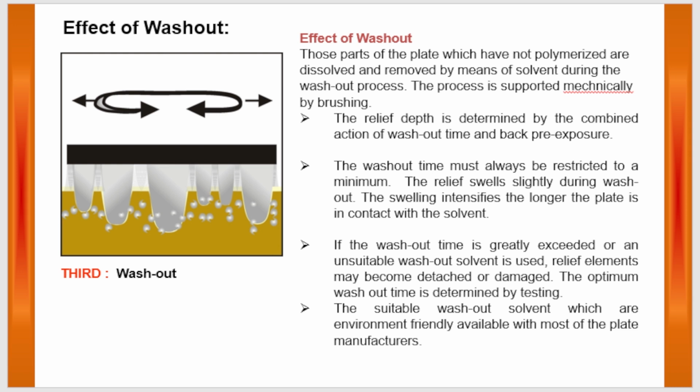The swelling intensifies the longer the plate is in contact with the solvent. If the washout time is greatly exceeded or an unsuitable washout solvent is used, relief elements may become detached or damaged. The optimum washout time is determined by testing. Suitable washout solvents which are environmentally friendly are available from most of the plate manufacturers.